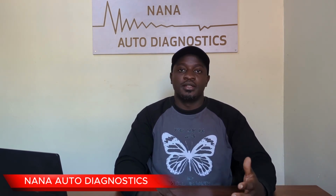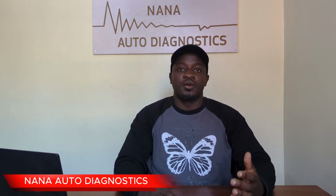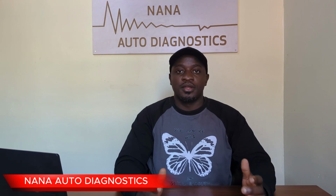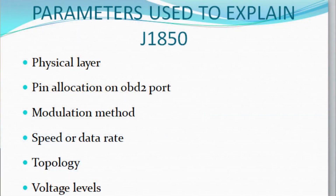So let's go ahead and explain each in detail, and we shall begin with the J1850 VPW, which is variable pulse width. We shall explain both based on these parameters, which include the physical layer, the pin allocation on the OBD2 port, the modulation method, the speed or data rate, the topology that is employed in each, and the voltage levels.